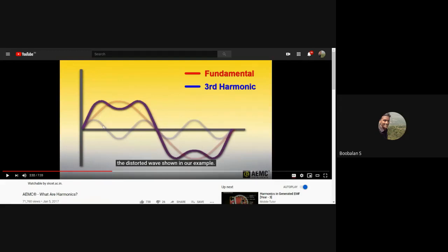Non-linear loads in the sense we are using SMPS, right? Switch mode power supply in computers. We have variable frequency drives in our induction motors. So what do they do? Switch mode power supplies and variable frequency drives, their operation has power electronic switching devices inside. Based upon my electrical load demand, it will adjust its power supply as well as total power supply. In this computer, the hard disk needs one power supply, the keyboard needs one power supply, and the display needs another. My switched mode power supply converts my input power supply of 230 voltage to different voltages for different loads. So its major role is played by my switching devices.